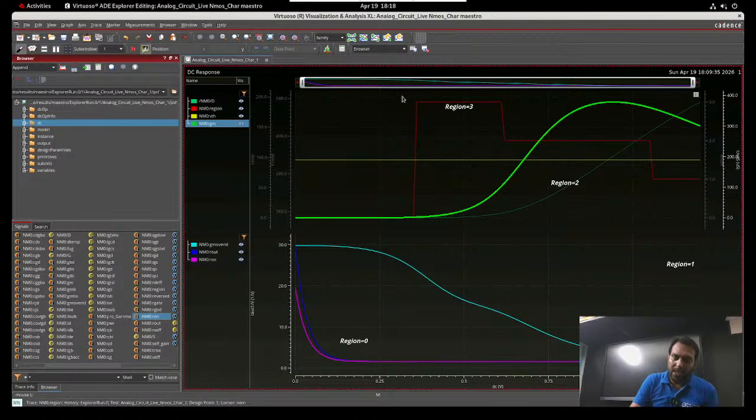If you open the plot in the browser, you will find every value of the VGS variation. Region is important, gm over id is important, gm is important, R on or R out is important. That's why I am showing all those values. There may also be the transient frequency, or Cgg, but I am not going for those now.